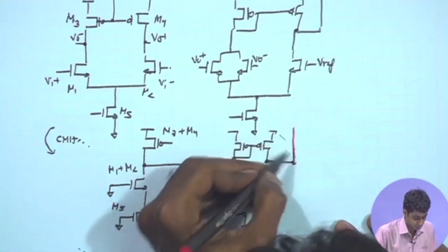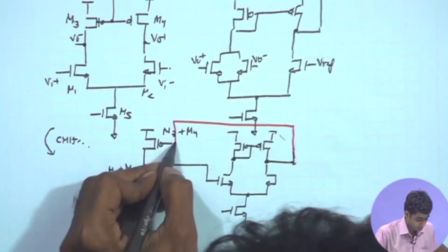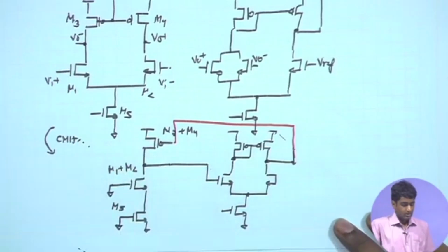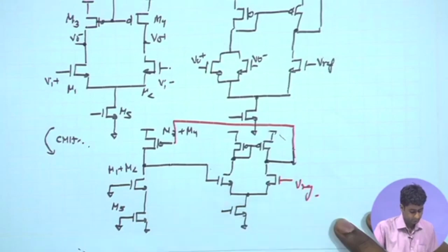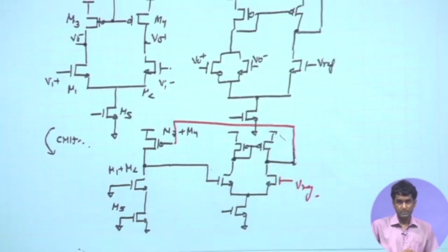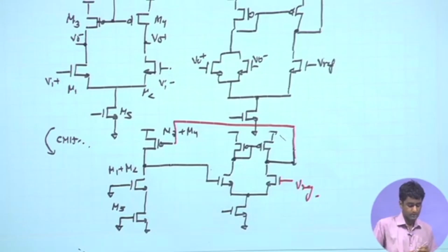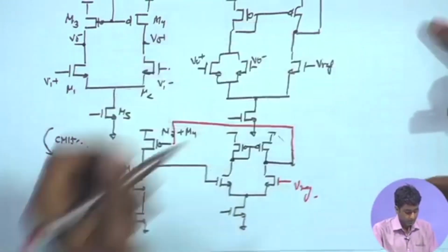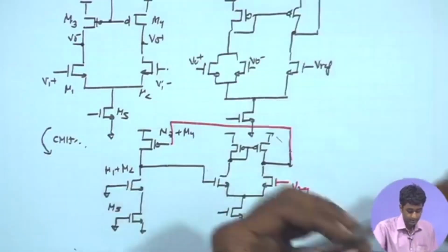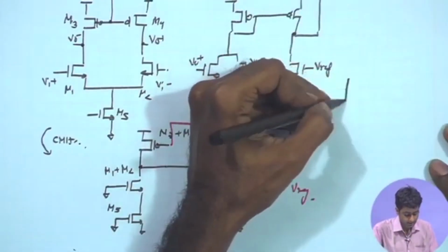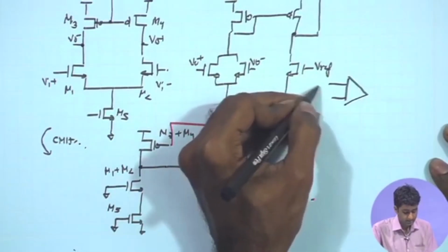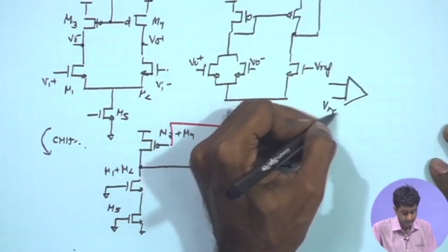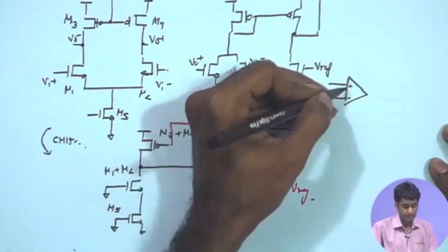So, just to keep things separate, here we have the Vref. So, here if we look at the overall operation, if we remember our analysis, if we represent this error amplifier as a symbol and then look at the terminal definition, we had said that the reference signal is at the negative terminal and this one is at the positive terminal, right.